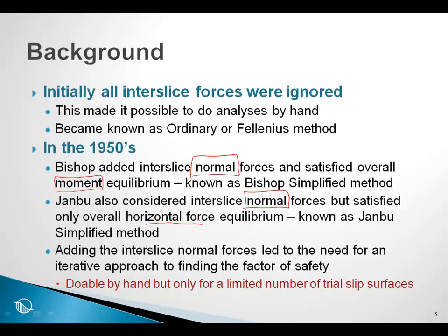Adding the interslice normal forces led to the need for an iterative approach to finding the factor of safety. This is doable by hand, but only for a limited number of trial slip surfaces. Any of you who have taken some graduate courses in geotechnical engineering have in all likelihood had to do this by hand or through the use of a spreadsheet.